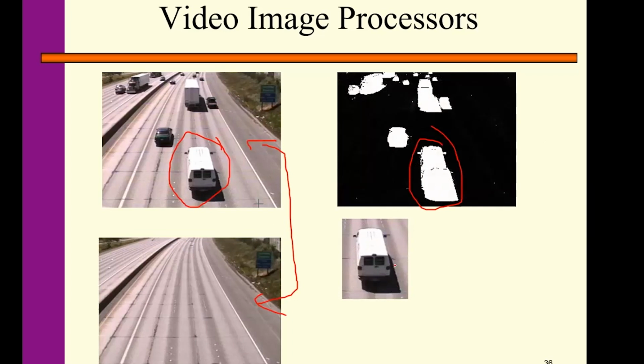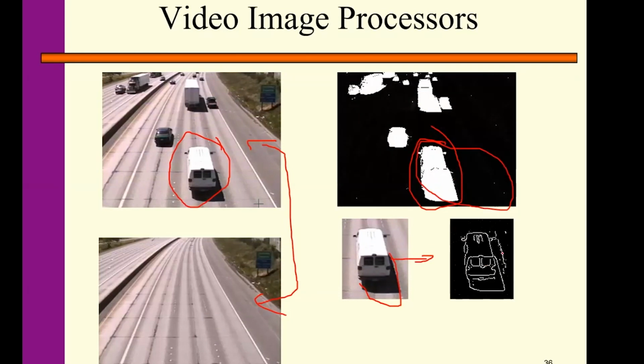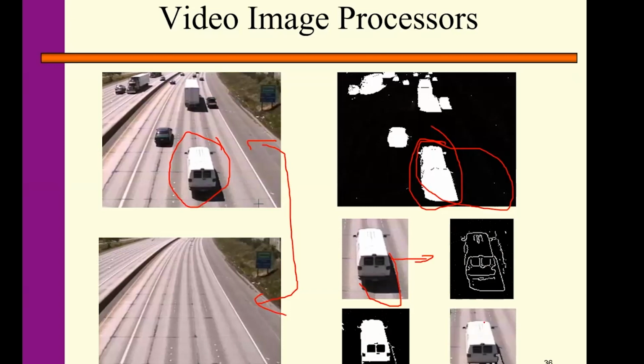There are many challenging issues associated with video detection, for example, shadow impact. If I have a strong shadow, the shadow will extend to the adjacent lane. If you have objects like this, it's hard to distinguish whether it's the vehicle or the shadow, so you can easily cause false alarm detection. We have to identify the edge of the vehicles and remove the shadows as much as possible, and eventually detect the vehicle only, to make the detection accurate. Those are the issues associated with the detection algorithm.